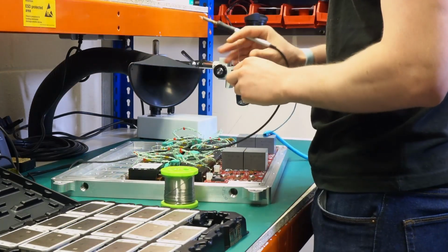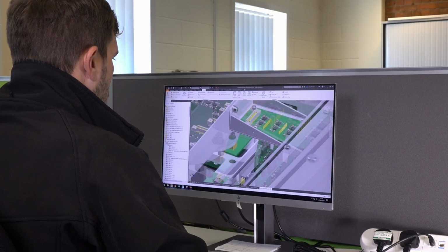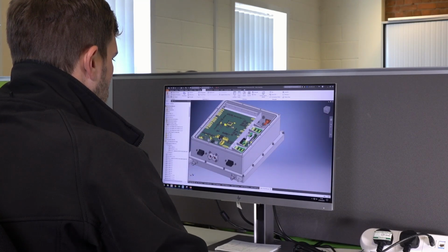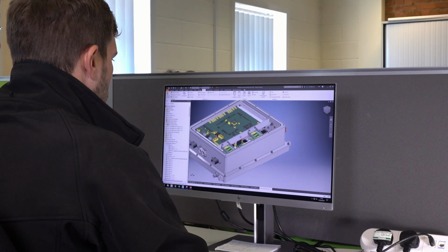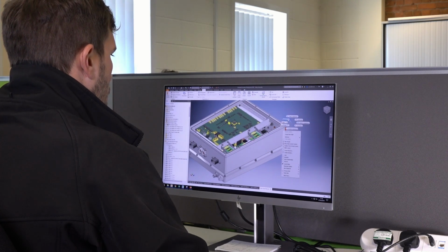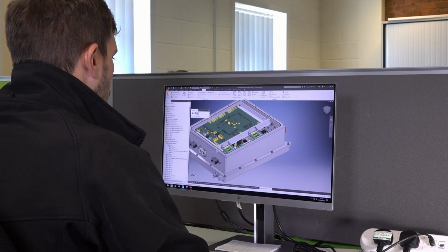That increased dV/dt and dI/dt that we get from the higher switching speeds has that knock-on effect of overshoots, so any parasitic capacitances and any loop inductances that we have, that's gone to another level, the care and attention that we have to take in the packaging and the componentry that goes around the main switching transistor to create the power converter.